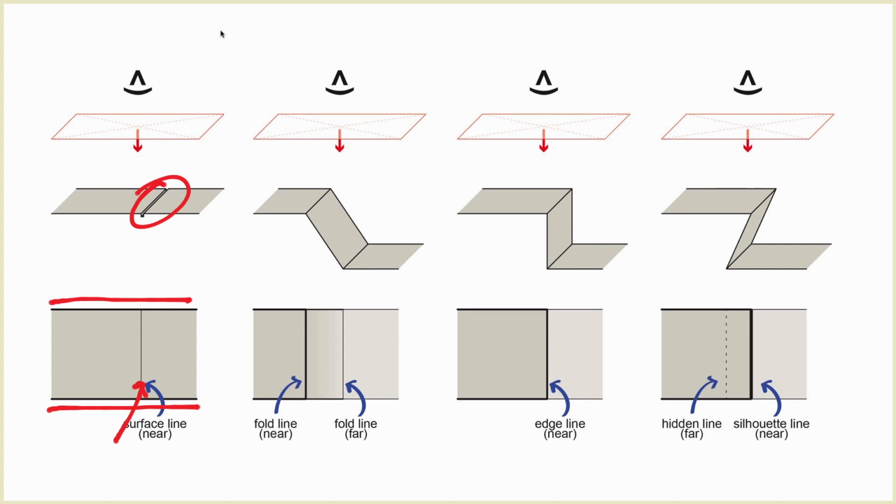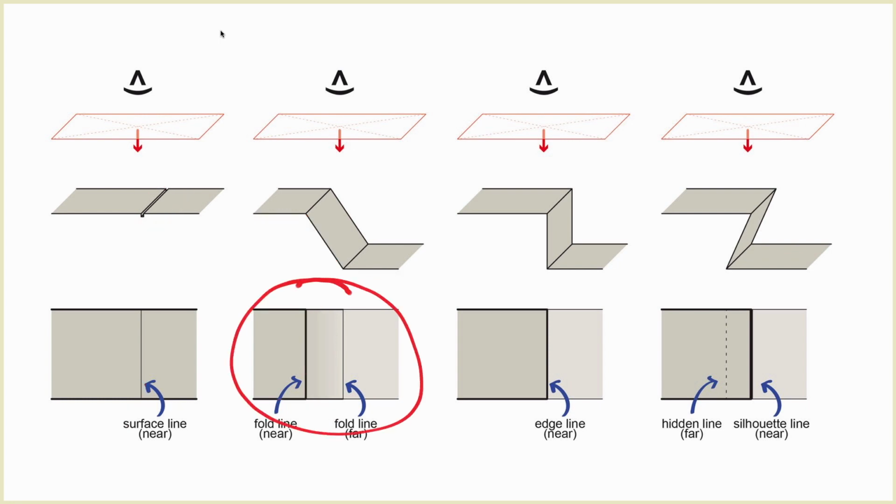If we move over to the next section here, number 2, this slopes down and away from us. As we look at it, the darkest line is here, here, and here. The next line would be there, and that line there. And our lightest line is down at the bottom. As we look at that drawing right here, we can see what's closer to us because it's darker and what's further away because it's lighter. So just by the line weights, we could tell that there's depth there. Do you guys see that? Next one over here.